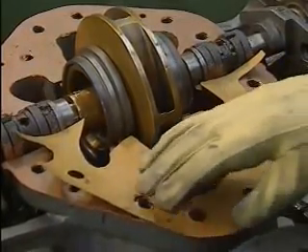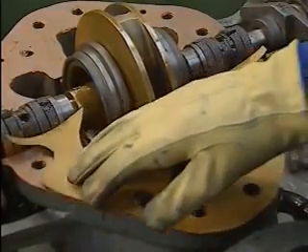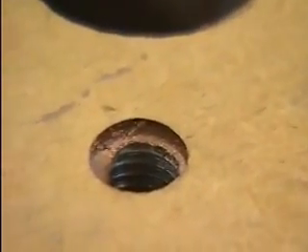He carefully lines up the gaskets with the edge of the pump casing and checks to make sure that all the bolt holes in the gaskets are properly aligned with the bolt holes in the casing. If the bolt holes don't line up perfectly, the holes can be punched again to slightly enlarge them. Forcing bolts through holes that are incorrectly positioned could cause the gasket material to tear, and the gasket might fail as a result. If a gasket is torn during installation, it should be replaced.